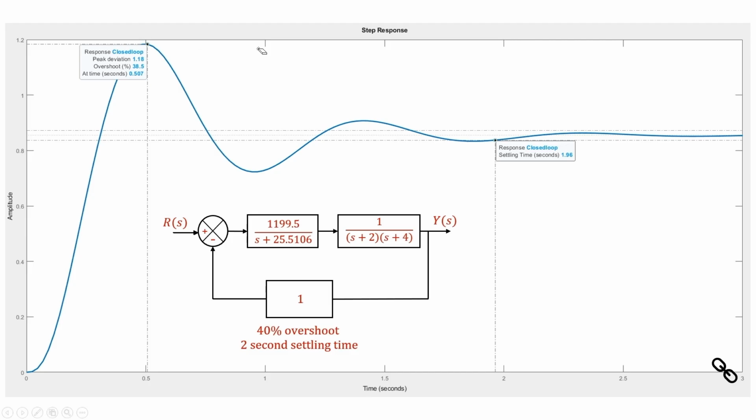This looks completely fine, right? I mean, this should work. The steps that we have followed are almost similar to what we did in the last lecture for the quadrotor example. Only thing is that now there is no zero, but there is an open loop pole that we are introducing, so that the root locus passes through the desired pole locations, the locations which we want to be dominant poles.